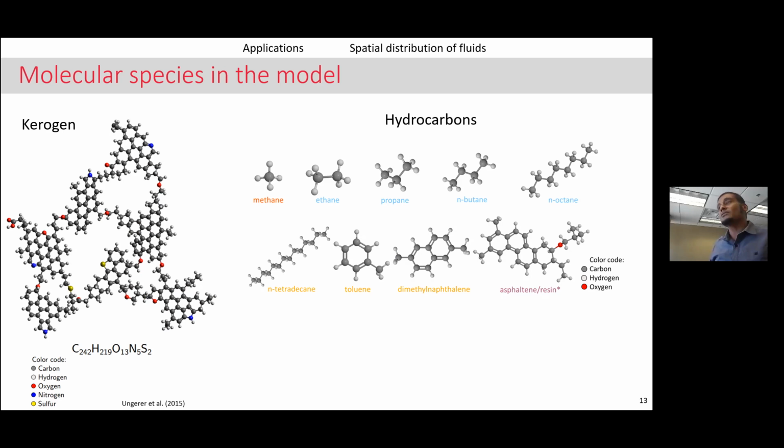You're absolutely right. The only way you can ascertain that perhaps nothing's going wrong is to ensure that when you're done with your simulations, you have reached what we call equilibrium. So the pressure looks like it's flattened out, the temperature looks flattened out, the energy levels look flattened out. Of course, we can start with an initial configuration that would bias you towards what you think might be the correct solution.